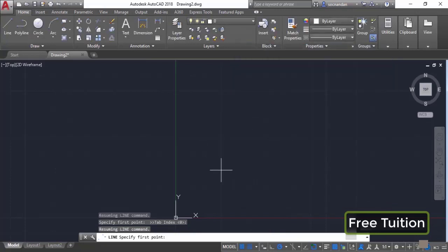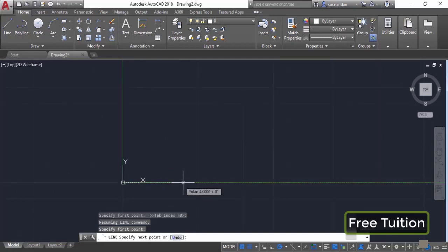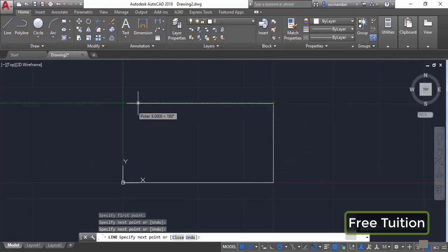And now we'll make a simple geometry. I'll make a simple rectangle in this case with a length of 10 and width of 5 units. So I'll click on this point, and we don't need to be concerned about the point because it's exactly clicking at the intersection of the grid line. Now click here, that will be the 10 length, and also we have this 5 length, the 10 length and 5, and now press enter.